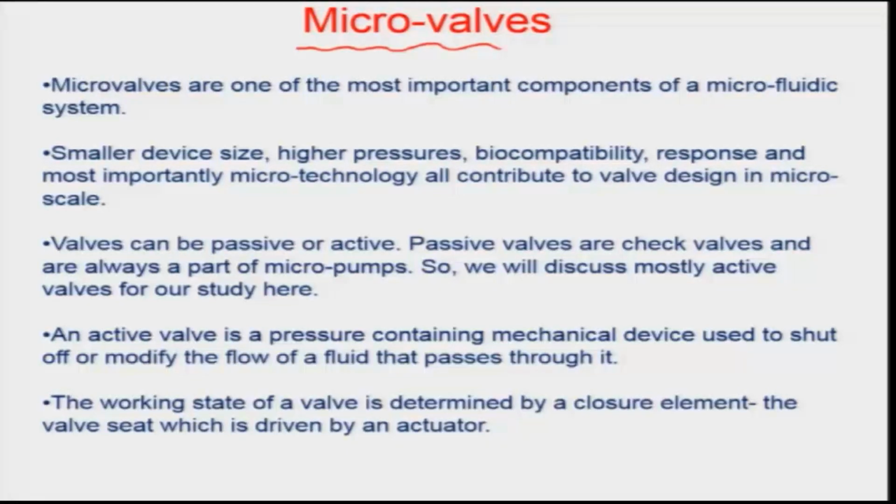So, let us look first at the microflow side of the story and how that can be controlled and guided. The first instance which comes to mind when we talk about actuators is microvalves. They are very important for maintaining microscopic flow. There are smaller device sizes. When we talk about such microvalves, there are challenges like very high pressures. With small sizes and higher pressures, you must be able to block the flow under normal conditions, so the design really has to be very, very robust.